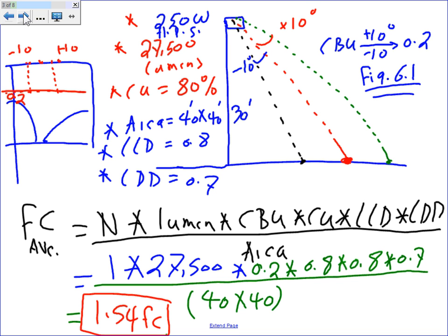If you have a 40 by 40 area, you put the fixture at one side of it and aim right in the middle of that square. That's your aiming point to get you the best distribution, more or less, across the whole area. I'm pointing right to the center of that square. If I aim further or lower, it will give me more or fewer lumens, which gives you a beam utilization factor.